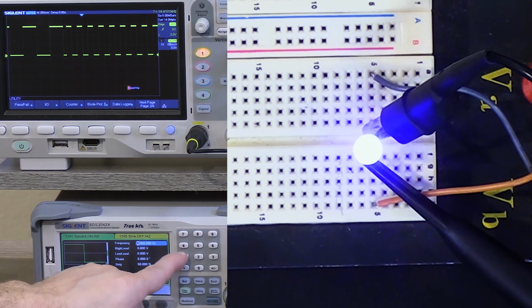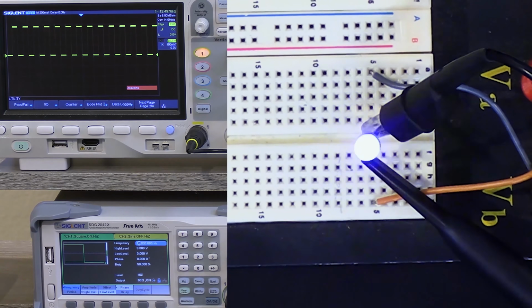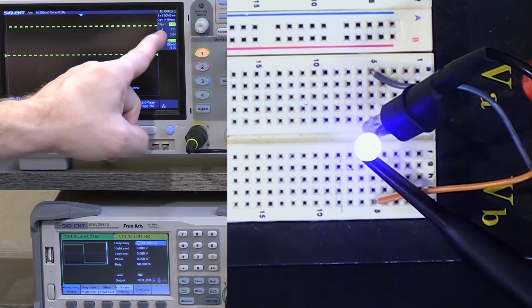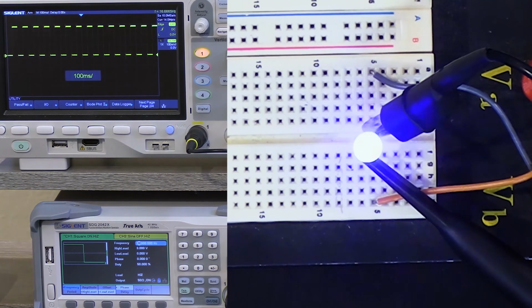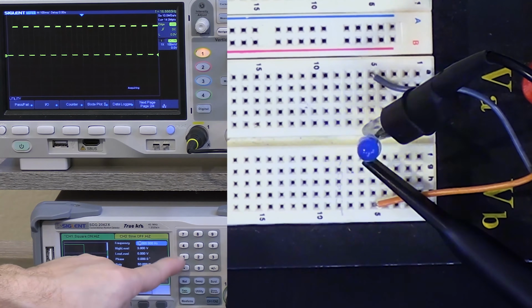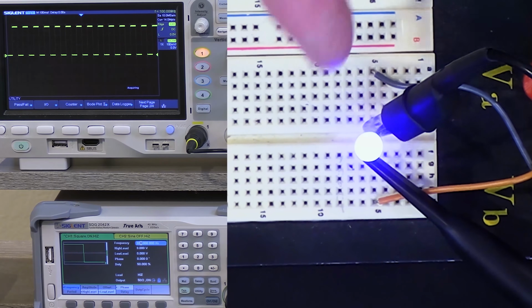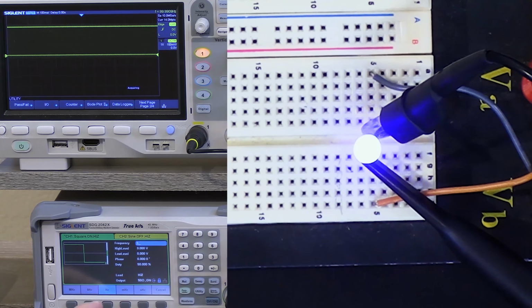Now, if you get crazy and start doing things like 10 hertz, then it's so fast that you can't really see it much anymore. You can barely see it here. And notice that our pulses got very, very narrow. And you would have to turn the knob here to be able to spread them out to see them anymore. If you drive this thing with like, I don't know, 100 hertz, it's going to be so fast that we're not going to be able to really even see. The diode just looks like it's always on, right? So let's go back down to 1 hertz.